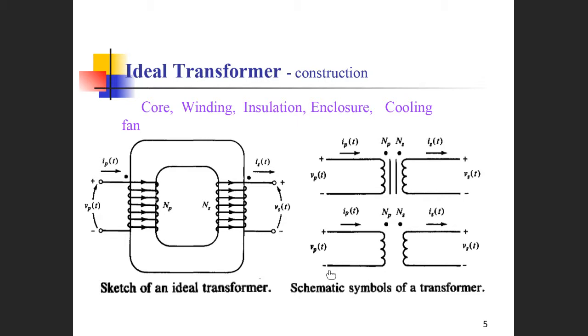So although polarity, positive and negative, is relative in AC systems, for the transformer, when we mark a negative end, this end is most likely to be earthed or bonded to the protective conductors. That's the difference, although the voltage on it, in comparison with the other end, is sometimes higher and sometimes lower. That's the meaning of it.